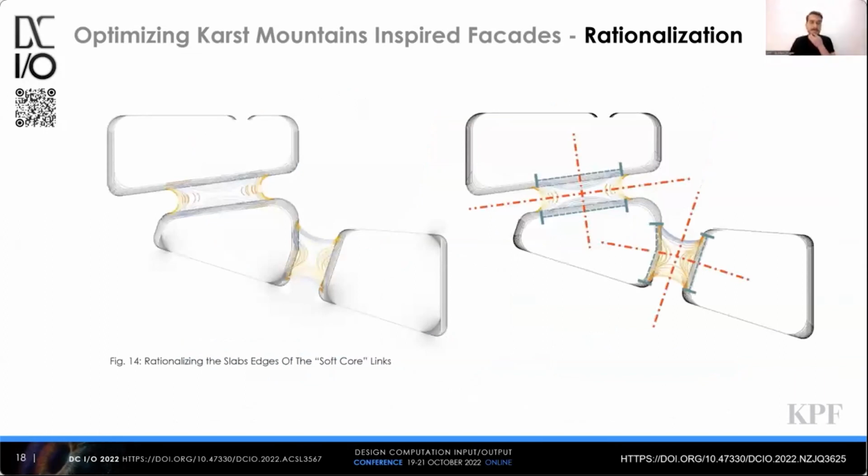And for wall type 2, we had to come up with a very simple logic. Every single arc that you are seeing here was defined in Grasshopper between these buildings. So we had to work out where this connection happens, how we can prevent having strange tangent points which coincide with the curvature coming from the corners, and how we create those symmetry axes to describe this geometry with fewer and fewer arcs.